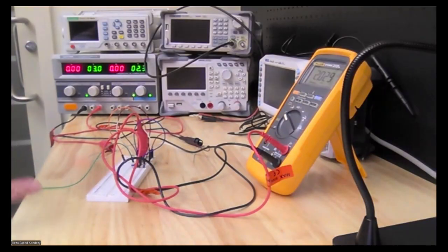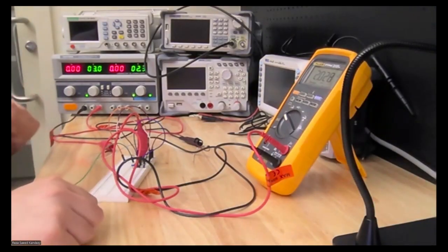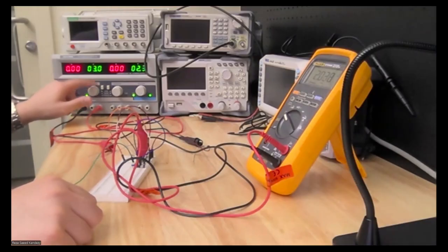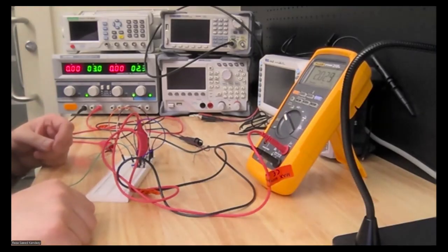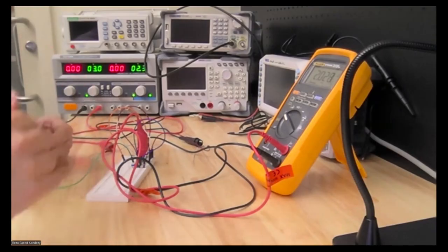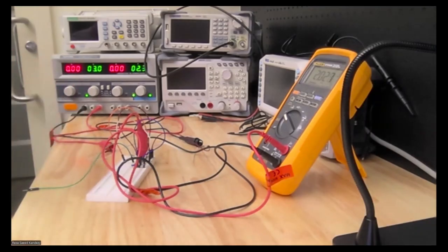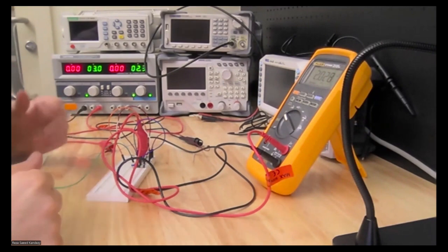Now you need to have at least 10 points for the data. So now you have the curve for that 10 microamp base current. Okay. After that, you would change the voltage source. That way, you have another base current, and you repeat the whole process. Now you have your second curve in the IV characteristics, and again the third curve. It is a little bit time consuming and energy consuming, but this is the way that you can actually create that IV characteristics based on the measurement.